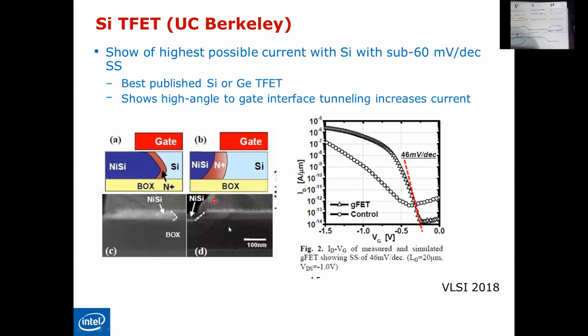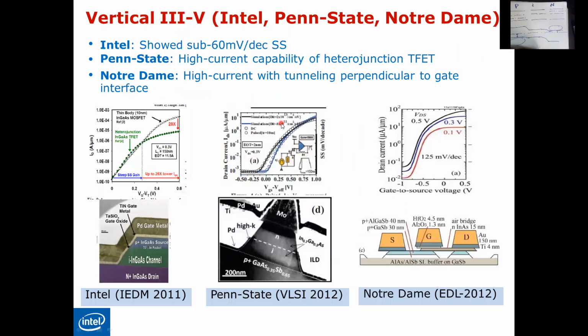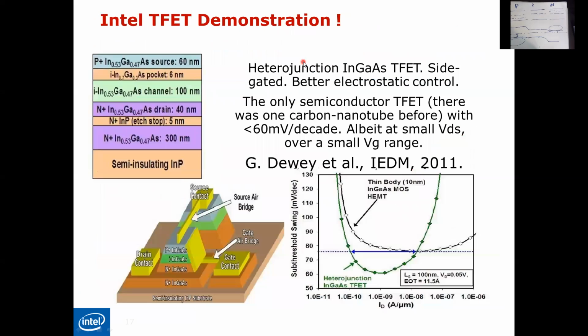Herein is our structure. This is what's called a scanning electron microscope image of these structures. This is a silicon TFET, I mean a TFET implemented using silicon, and this is the corresponding IV curve for this structure. Of course, this is for your knowledge. And here are also other structures or other materials that can be used in order to implement the TFET. Again, these data have been captured totally from the Intel website. So these are different Intel transistors using the TFET technology.